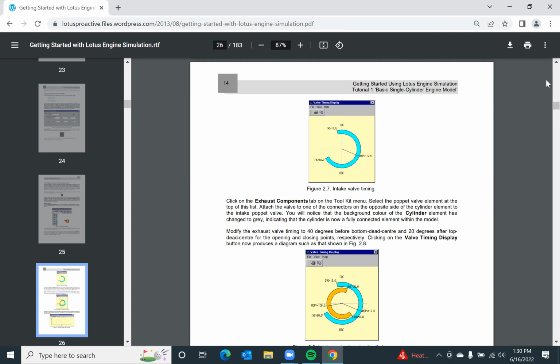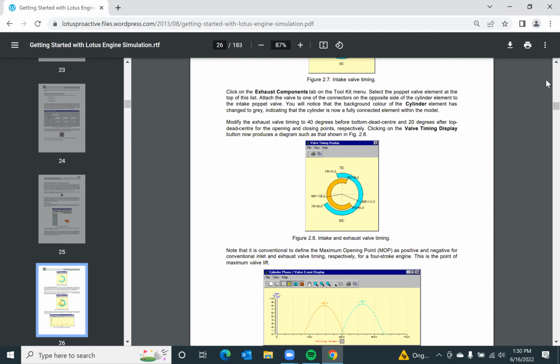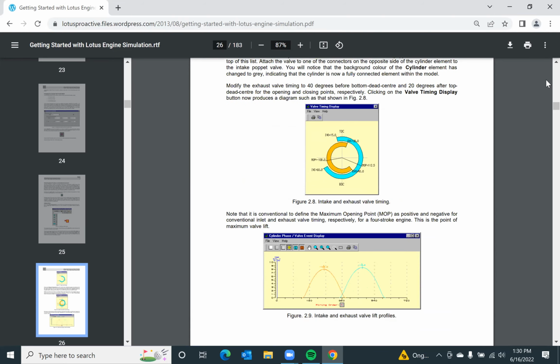So all these small details are super important, and you need to have some practical experience. But then valve opening and closing profiles also play an important role. Do you want a bang type of opening, like valve open, close, or do you want gradual opening? If you want gradual opening, do you want the opening to be slow or fast initially?